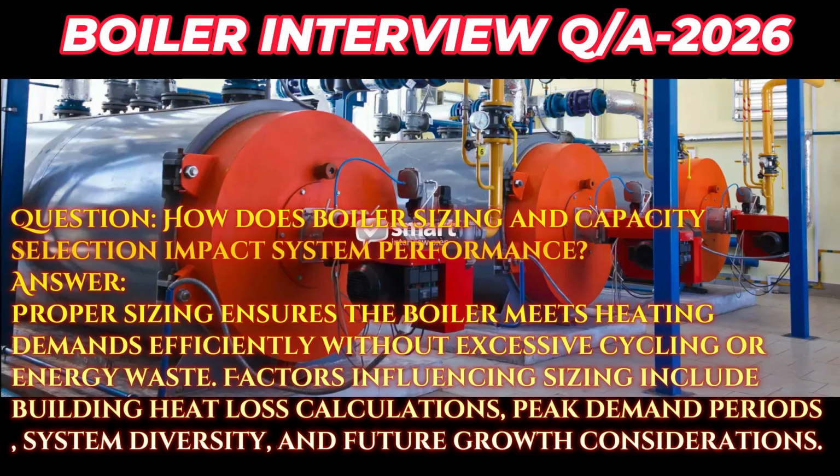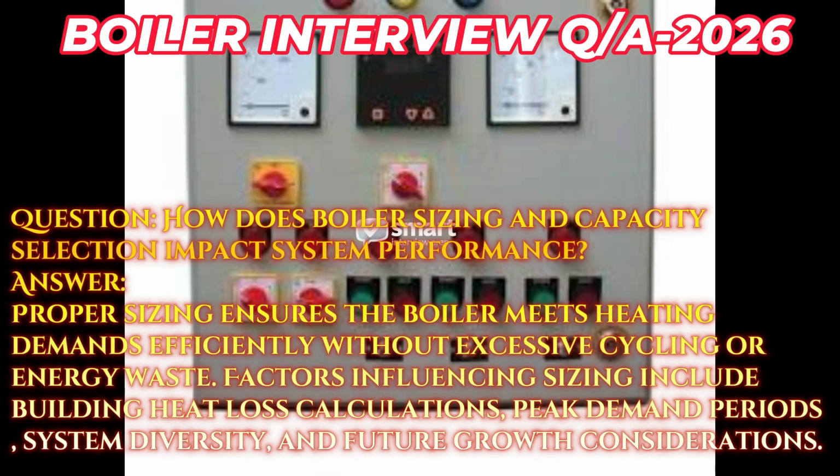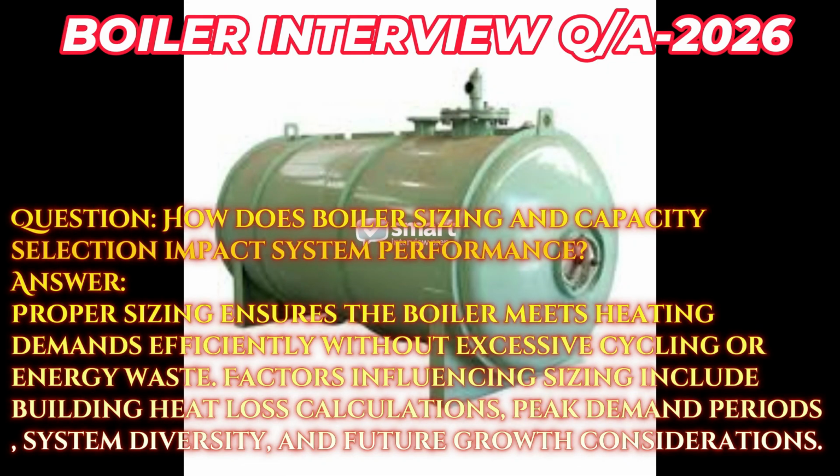Question. How does boiler sizing and capacity selection impact system performance? Answer. Proper sizing ensures the boiler meets heating demands efficiently without excessive cycling or energy waste. Factors influencing sizing include building heat loss calculations, peak demand periods, system diversity, and future growth considerations.